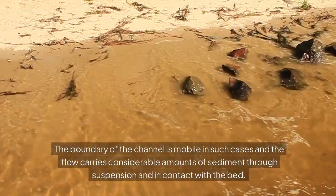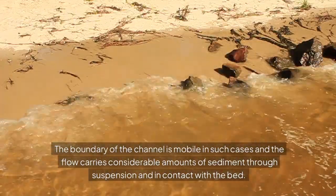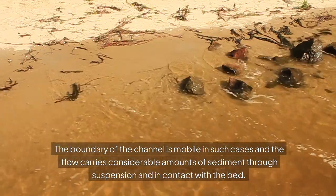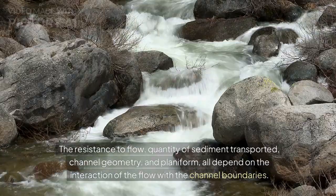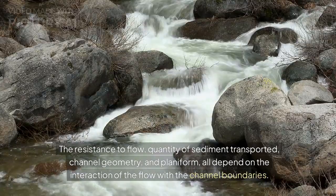The boundary of the channel is mobile in such cases, and the flow carries considerable amounts of sediment through suspension and in contact with the bed. Such channels are classified as mobile boundary channels. The resistance to flow, quantity of sediment transported, channel geometry, and planform all depend on the interaction of the flow with the channel boundaries.